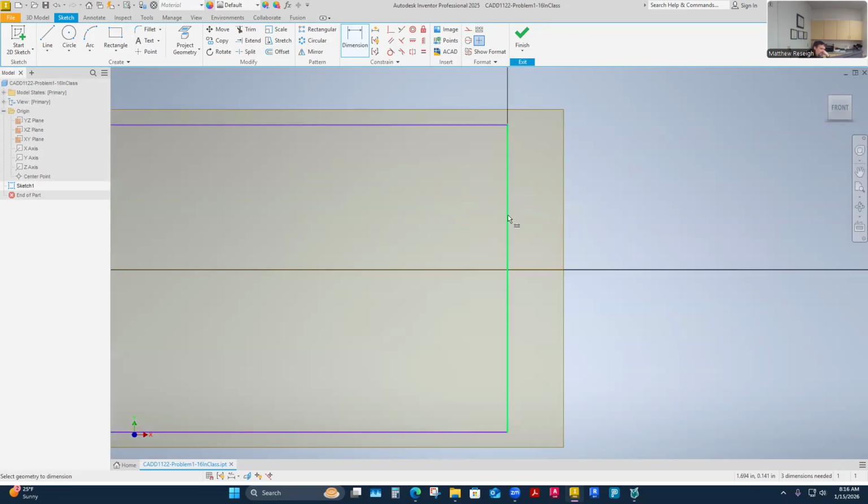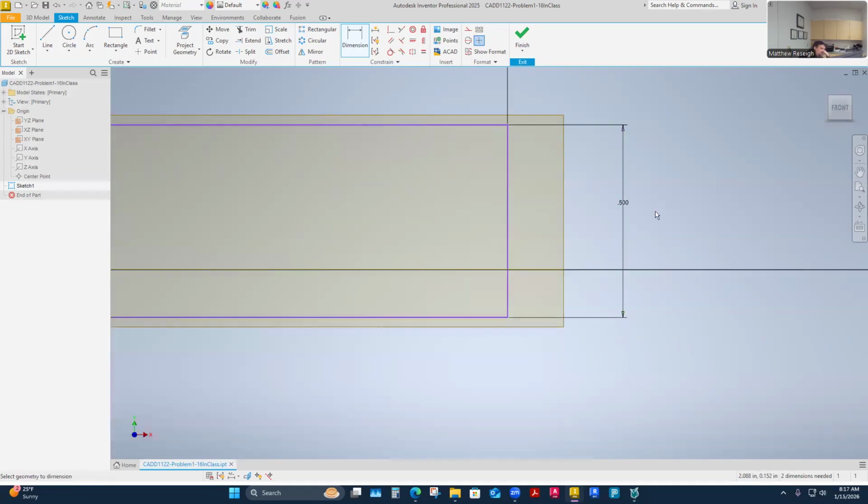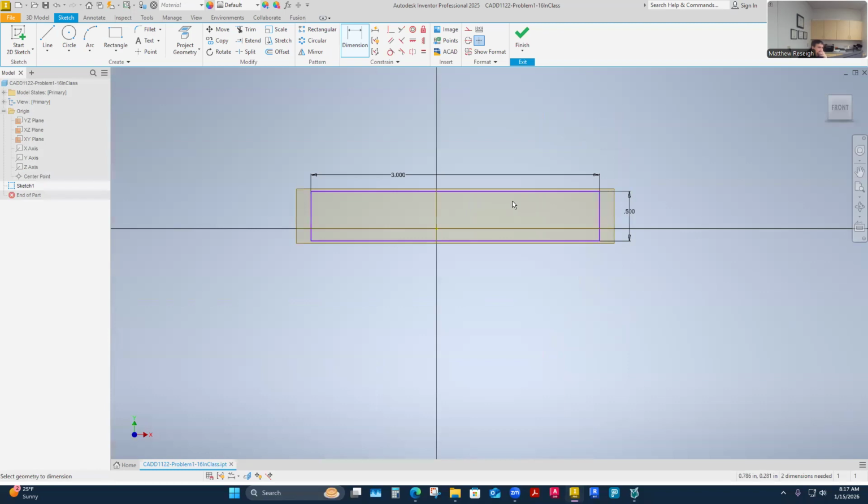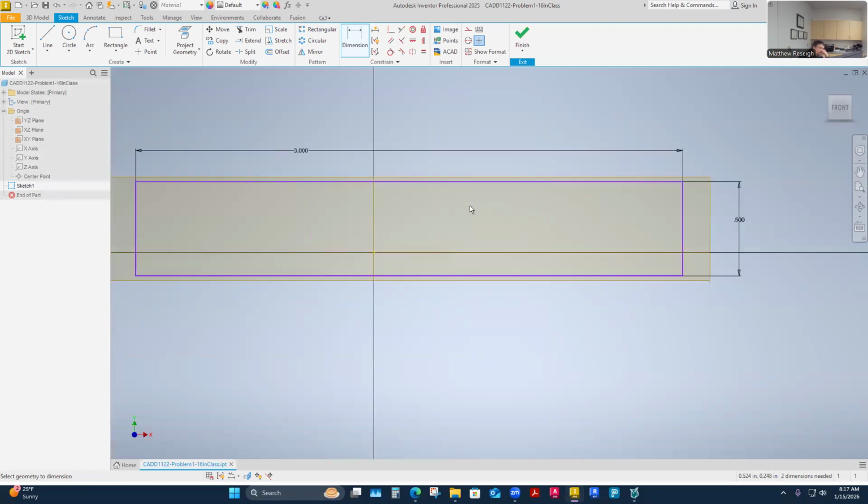And then it's 1/2 inch this way. So I'll show you another way that I constrain stuff. You see me just pick a point on my object and then do a coincident constraint and lock it into the center point. Sometimes that's all it takes to constrain this thing. Dimensionally, this thing is constrained. Just needs to be constrained in model space.